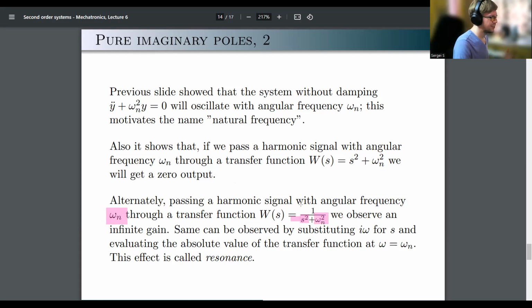So what will happen is the transfer function will become 1 over 0. So it will tend to infinity. The Bode plot that you would plot here would have a response going to infinity. Bode is normally defined for stable systems. This is marginally stable, so it's dubious to draw a Bode plot for it. But this is for amplitude response, and we could plot amplitude response without Bode. For amplitude response, it is a classic.